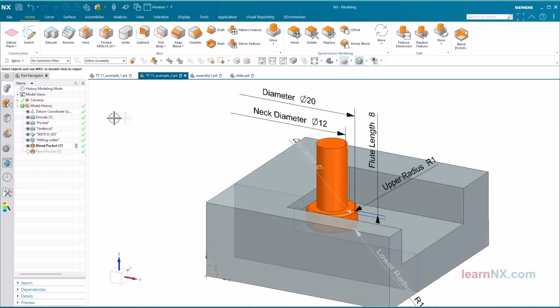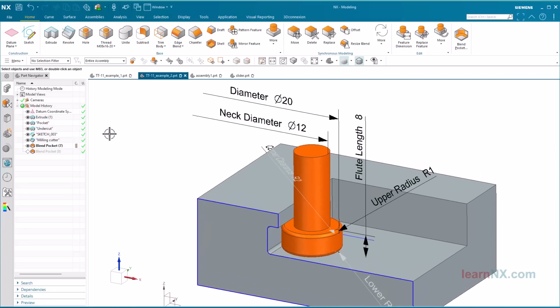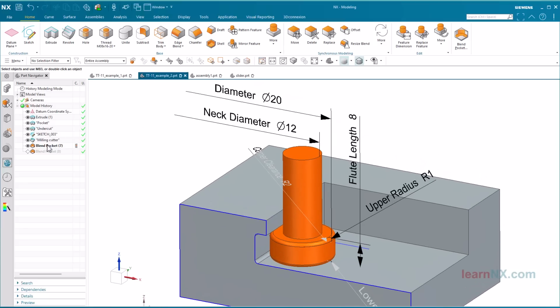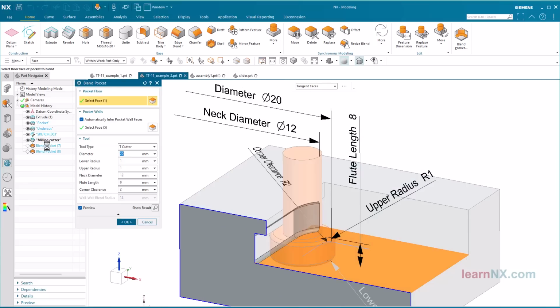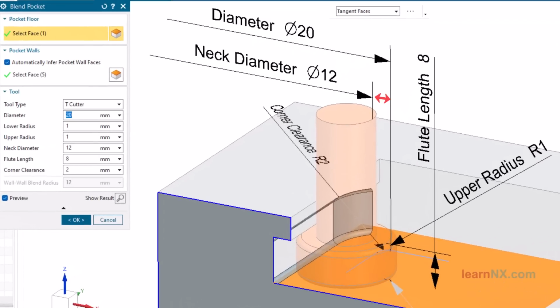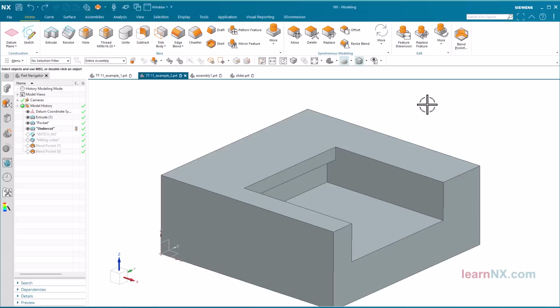Undercuts can also be created with a T-cutter. Just to be able to explain the settings better, I designed and dimensioned this milling cutter again. If this distance is smaller than the depth of the undercut, an error message is displayed. And also, if this length is greater than the height of the undercut. This is actually quite logical and helpful, but a little confusing at first. This pocket also has to be created in 2 steps.